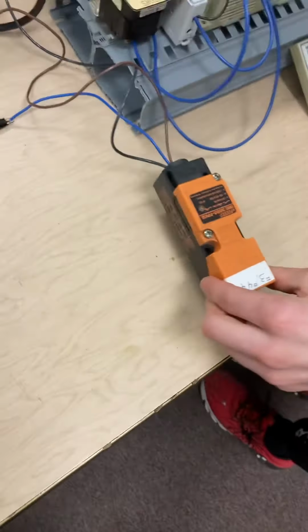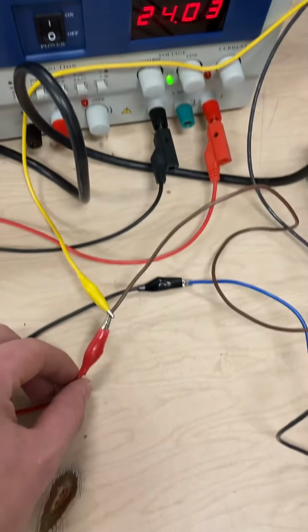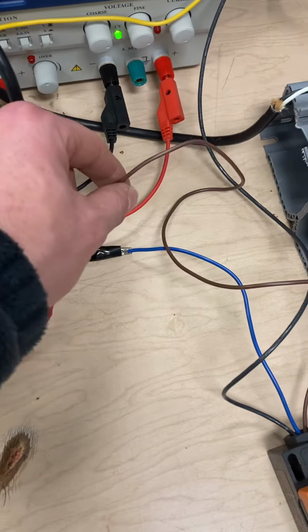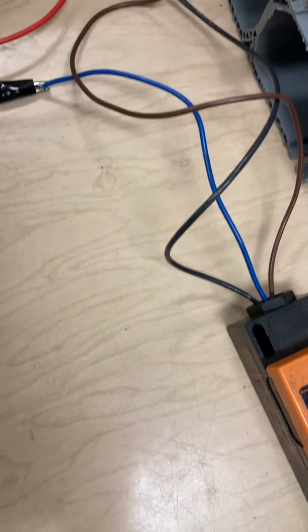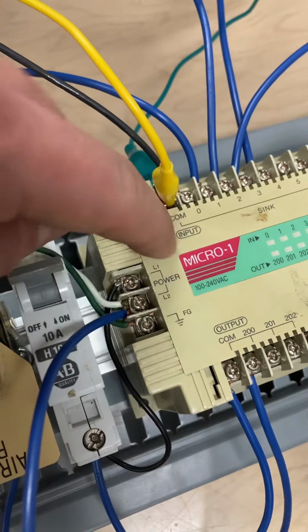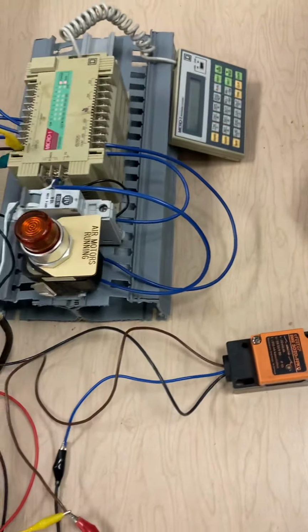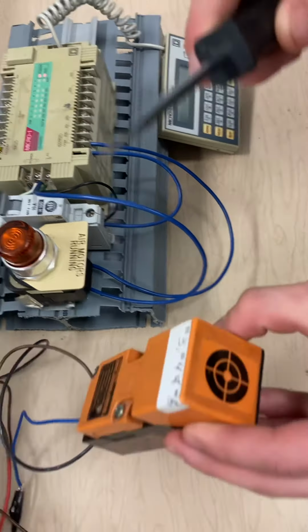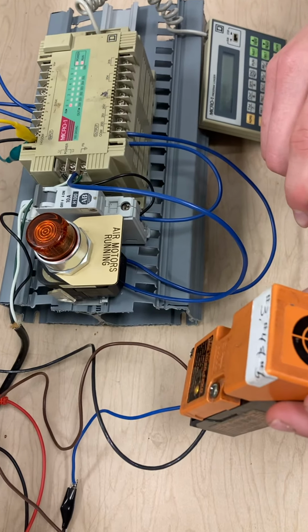So we wired up a sensor module here as well. We have 24 volts coming into it with this red line going on the brown cable. We have our neutral, or 0 volts, coming in on the blue cable. And then we have our black hooked up to 0 to give us the input there. And our 24 volts in jumpered over to our COM to power the internal power supply to make this whole thing work. You can see it here. If he puts it over there, then you can see the input command for 0, showing that that's working properly.